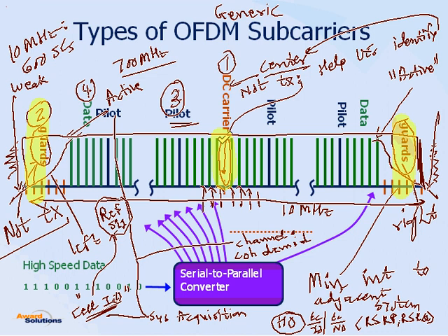So coherent demodulation is another function of pilot. So those are some of the uses of the pilot signal or reference signal in our OFDMA system. So the signal that is sent on the pilot is a function of the cell ID. We use that for pilot measurement, handover measurements, use that for channel estimation so that we can do coherent demodulation and so on.